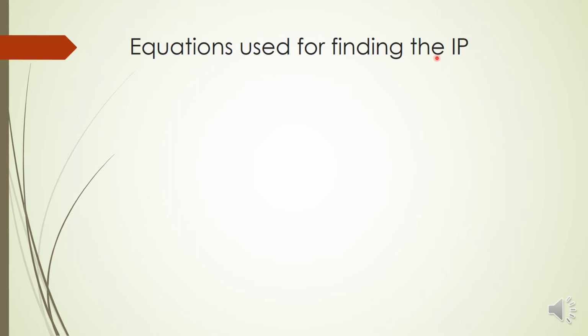In the lab, you might not have done this indicated power measurement because it is costly equipment. The indicator device requires three elements. First is a pressure sensor, required for sensing the pressure in one cycle. Then a piston displacement sensor, and a display unit. So three units are required: a pressure sensing device, a displacement sensor and a display device. Using these we can draw an indicator diagram.